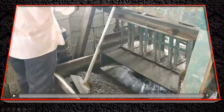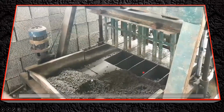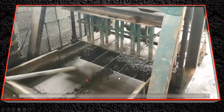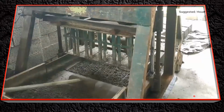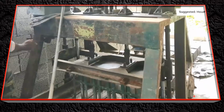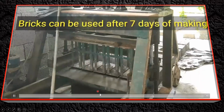So if I try to play this video, see here, this concrete that you have is very dry now. This is how the blocks are prepared. Now they're pouring the concrete into the mould. So this is very dry. There is hardly any water in that. See, now he's trying to put the pressure. This is called jolting here, and also he's applying pressure. So as a result of that, what will happen? It will get compacted, and you can see the blocks are ready here.